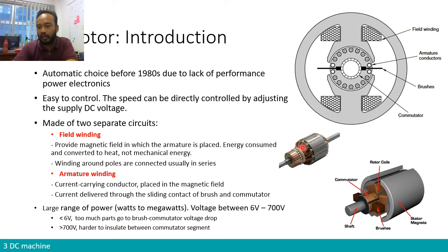You can see here in copper color is the conductor, and they are basically connected to this copper-colored surface as well. So this section is what we call the commutator. The commutator is basically the component that receives current and then delivers it to the winding. And how does this section receive current? It receives current by a sliding contact with what we call the brush. In this GIF animation below, we can see that you have a commutator in the middle, and in contact with the commutator is a brush. This brush is connected to a power supply, where current will go through the brush and, being in contact with the commutator through sliding, of course it's a friction contact, the current can be delivered to the winding inside the armature, or we also call it the rotor coils. Okay, so we need brush and commutator to deliver currents into our rotor coils or armature winding.